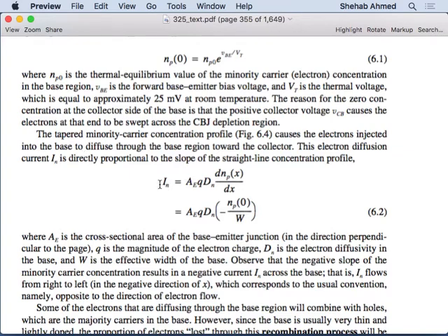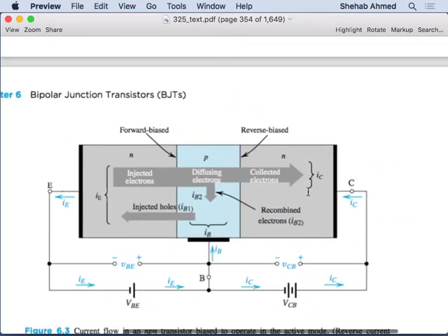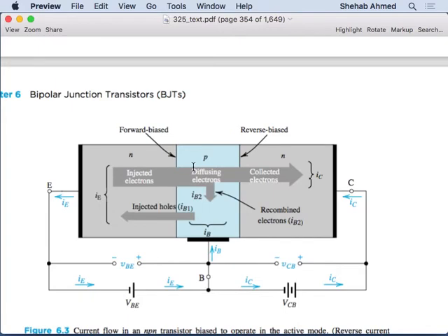So we will find that this will be equal to the collector current, and also be very close to the emitter current. So the emitter current and collector current will be very similar. Not exactly the same because of whatever's happening in the base. Some of the recombination that's happening in the base and the reinjection of holes makes a small difference between the current on the emitter side and the collector side. There's a small difference in current because of the electrons that are recombining after diffusing. Okay, but small difference. But all of these currents will be mainly due to diffusion, and they will all sort of follow the same equation of current as the diode. Okay?